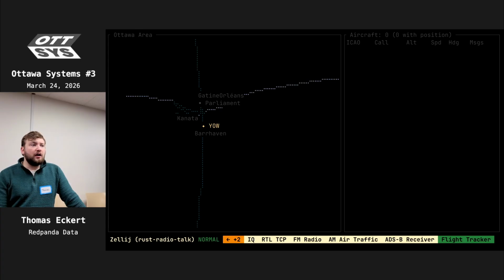So zero would be your carrier wave, which has what's called a base DC signal. Let's say the base DC signal is at +5. Then you add audio on top of it, and then you basically do biasing to bring it back down to 0. That is how you extract, let's say, audio from amplitude.